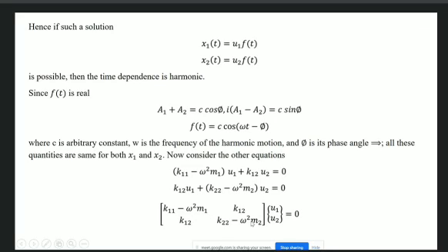That means if we write it in the matrix form, then on the right hand side we will have a null vector, and as I told you, this is the form of an eigenvalue problem. That means the stiffness term minus some lambda in the diagonal, and here also the stiffness term minus the same lambda. So this lambda is actually called the eigenvalue, and this kind of problem is called the eigenvalue problem.